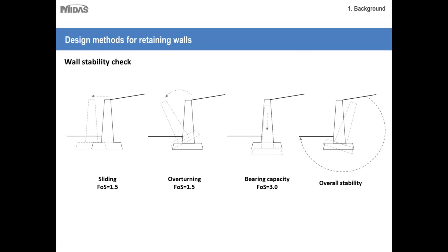And therefore there doesn't exist an empirical formula to determine this, and for this type of situation we have to perform a numerical analysis to assess how the slope would deform, or would it be stable by itself, or what will be the failure surface if such a failure occurs.